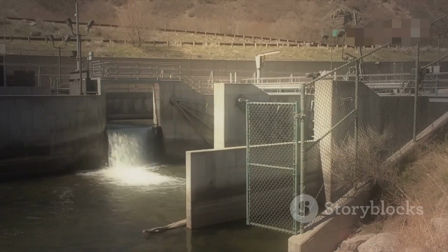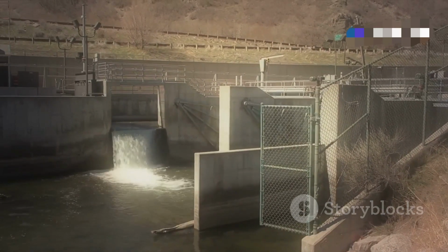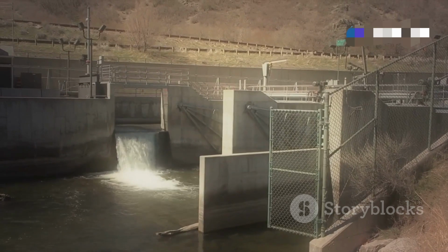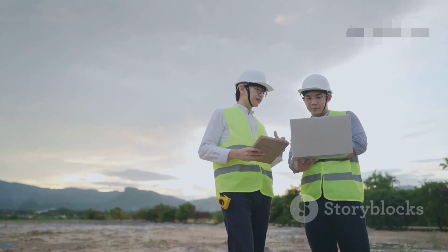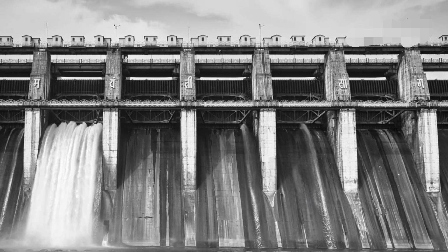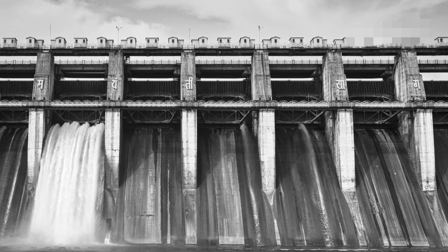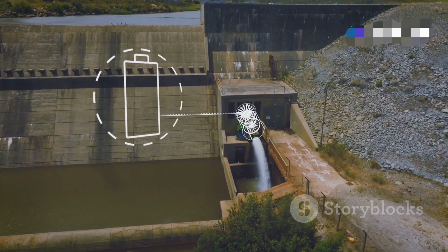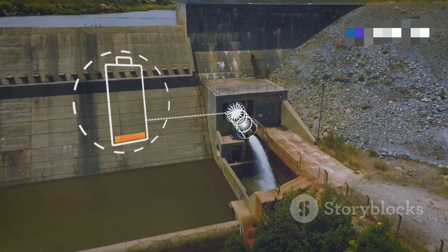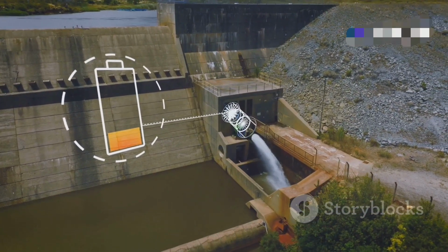For concrete dams, the development time might represent the time it takes for a section to topple or slide, which could be very short once instability occurs. Estimating TEF can be challenging. Engineers often rely on empirical equations derived from historical dam failures. These equations typically relate TEF to factors like dam height, dam material, and sometimes the volume of water.